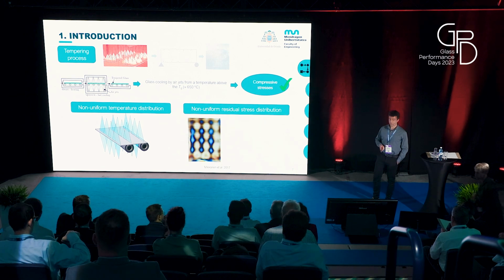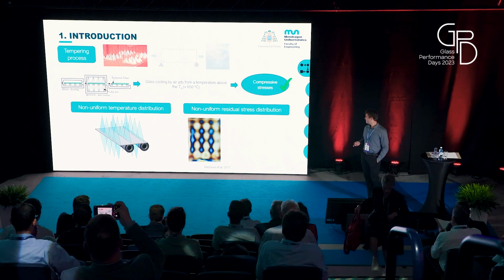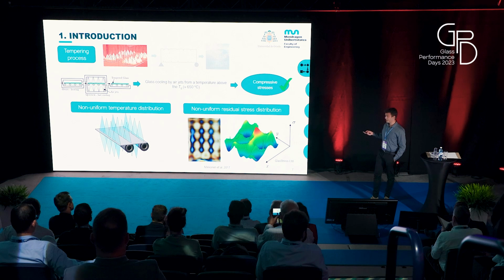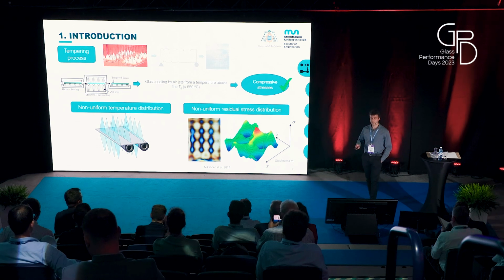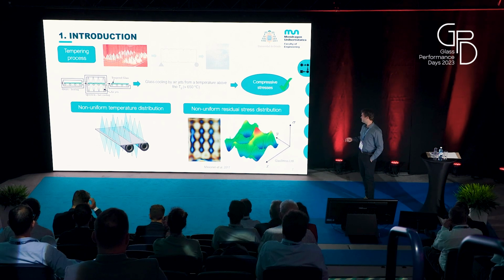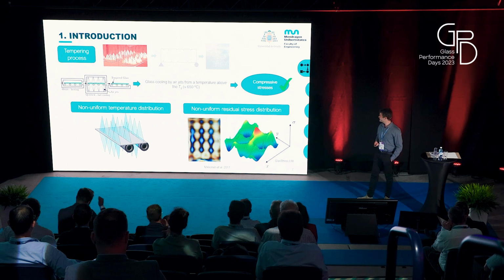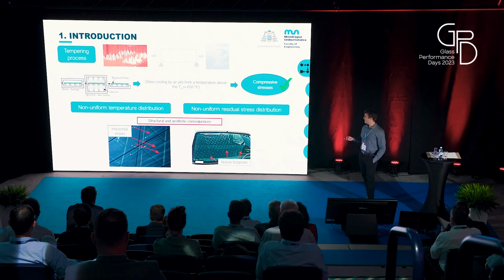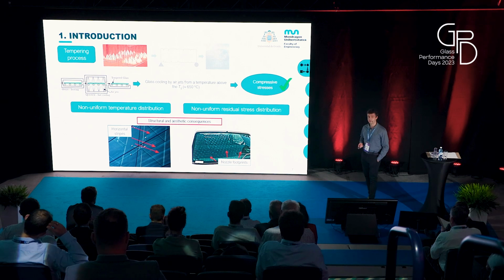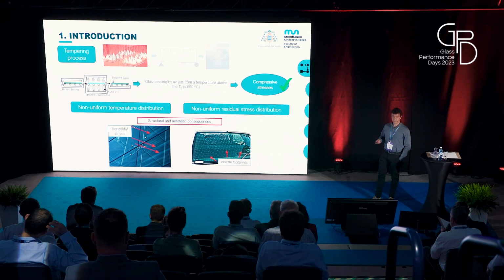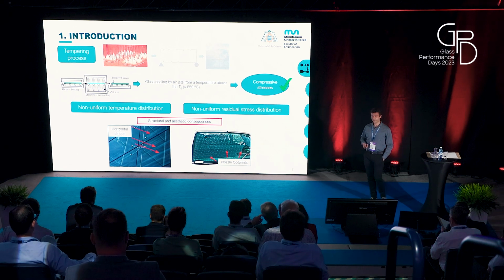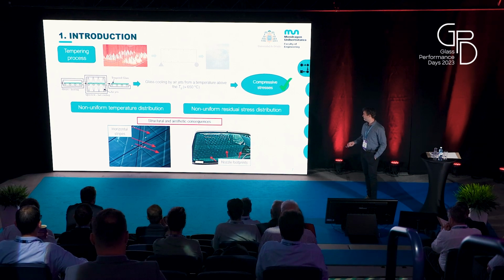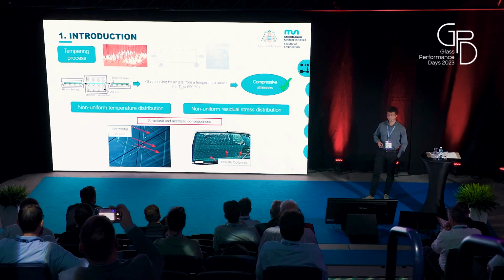As we can see by a polariscope, these non-uniform residual stresses, or here in a 3D measurement surface, we can also see these non-uniformities. These aspects have a direct impact on the structural and aesthetic features, and we can see this in the anisotropy that we can see in tempered glass panes, such as in building facades or in the rear windows of cars.